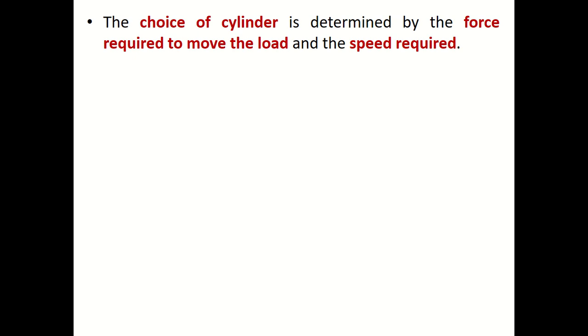Now, which cylinder to choose, and how to choose the cylinder for a particular application? Please note that the choice of the cylinder is determined by the force required to move the load and the speed required. Of course, there will be an end use for this pneumatic cylinder.